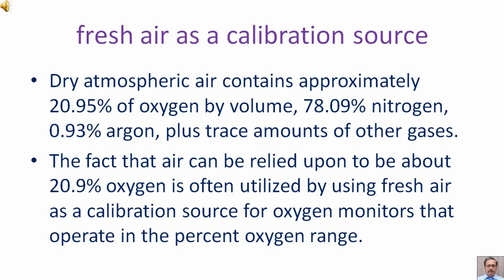The fact that air can be relied upon to be about 20.9% oxygen is often utilized by using fresh air as a calibration source for oxygen monitors that operate in the percent oxygen range.